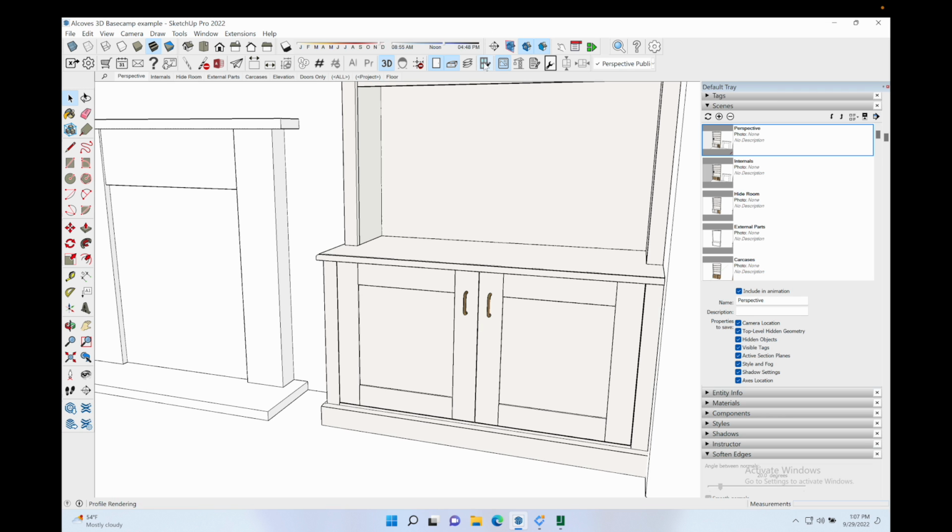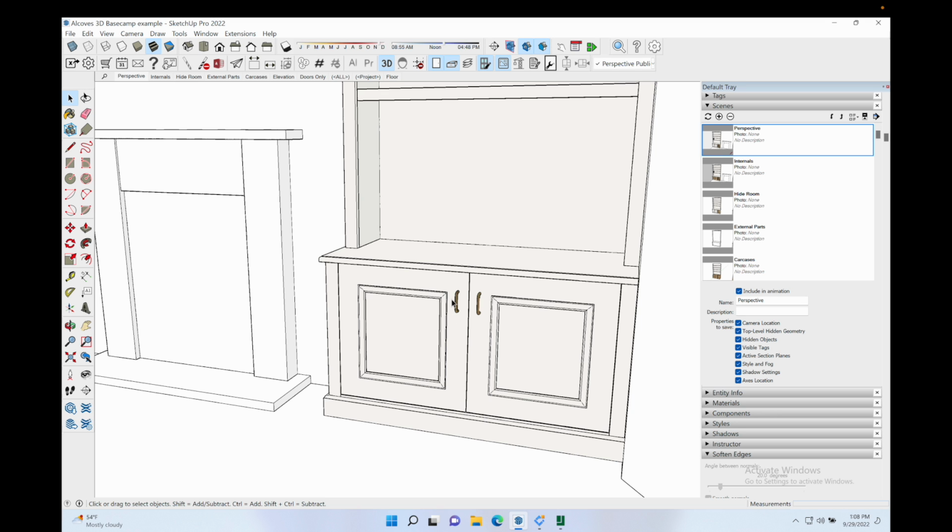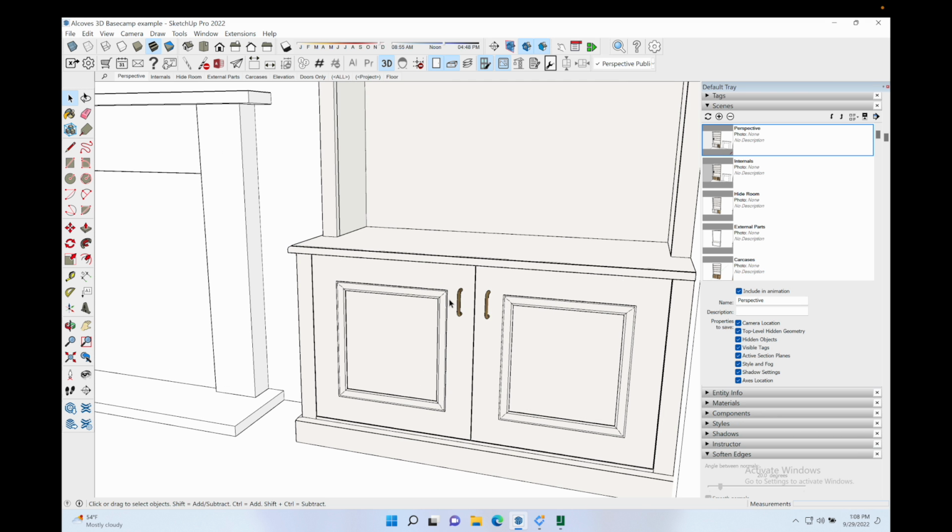I'm going to just use the CabinetSense toolbar up here and use this render door profile. So these doors have been told to use what we call our classic profile. That's a profile that I've drawn in 2D and saved, and then CabinetSense has just wrapped it around the 5-piece door which I've created. I can turn that off and go back to a 5-piece door.